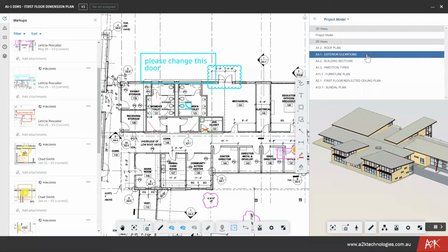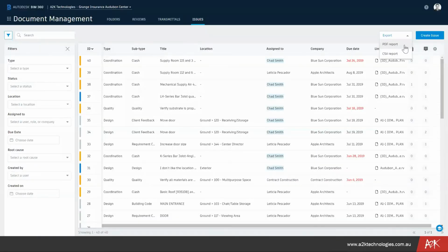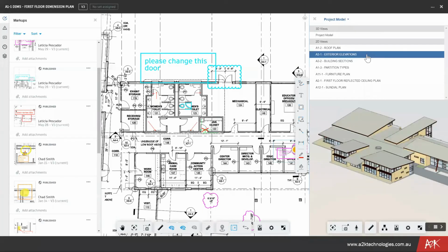The purpose of getting this information shared into BIM 360 is so that those non-designers can review the information, whether they are project managers, design managers, people out on site, even the customer themselves can have access to this information so that they can provide markups and raise issues. Issues in particular have a managed workflow wrapped behind them. That is to say that when an issue is raised, somebody needs to take responsibility for it so that it is ultimately resolved and closed out. Now, we're going to go through how issues work in this workflow process with Navisworks and Revit towards the end. But noting that issues in this case have a managed workflow, whereas the likes of markups don't.